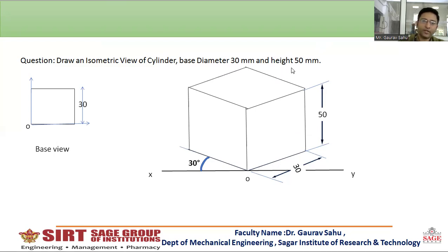In case of isometric, the top line is always visible, so I have drawn it with dark pencil. Remember that this is a portion of cuboid, not of cylinder, so I am drawing this with lighter pencil, that is 2H pencil. So remember that whensoever you are drawing a cube or cuboid for drawing the cylinder, pyramid, or prism, always draw this type of work with 2H pencil. Now the hidden sections of base and back line, these are the top verticals. From front they are visible, but this vertical will not be visible.